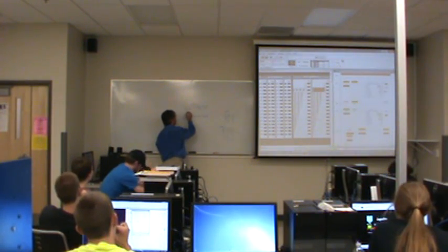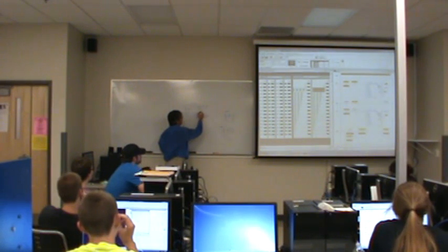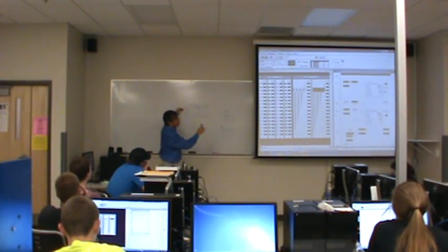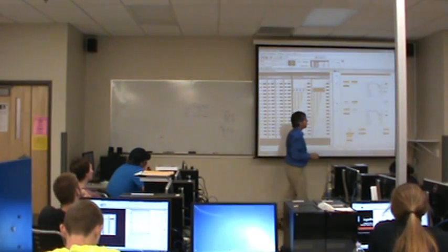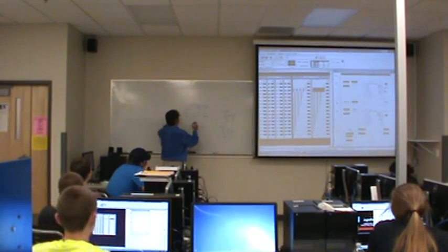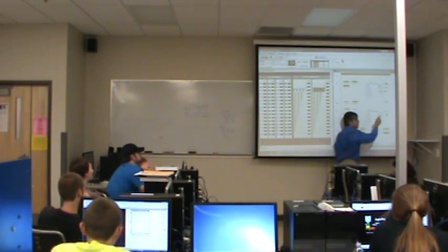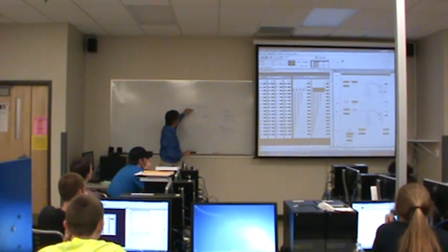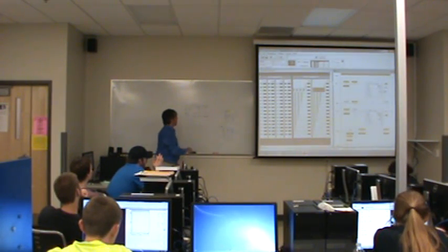Well, if I have a word in memory, let's put an integer in here. So an integer in memory location 0, I could put a 0 here, a 1 here, a 0 here, a 1 here, a 1, 0, 0, 1. And the mask will be applied every time either sequence compare or sequence output is running, whichever one it's associated with. It will always take the input word that I've specified, let's take compare for example, and before it tries to compare it with what's in memory, it will AND what it sees on that input word with the mask that I've told it to use. Does that make sense?